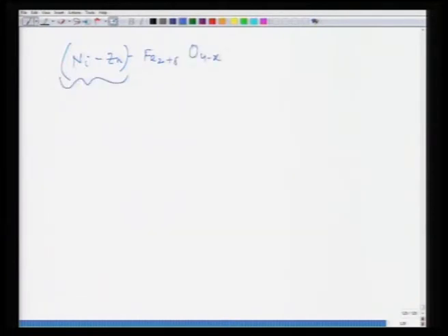So, you have nickel zinc ferrite, here iron is 2 plus delta, which means iron can be a little bit in excess or deficiency, which will affect the oxygen deficiency or excess, because as you know, if you change the composition of one cation, you are going to change the oxygen stoichiometry as well. So, this is a non-stoichiometric material, and this shows a change in the resistivity.